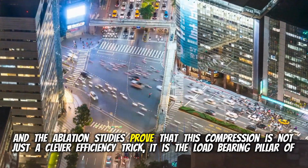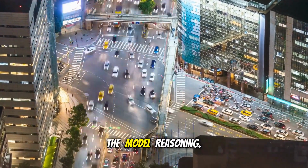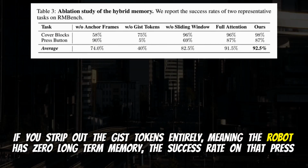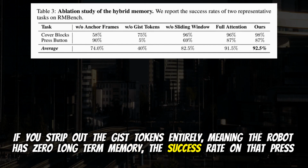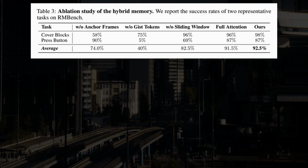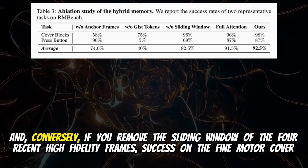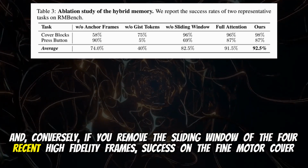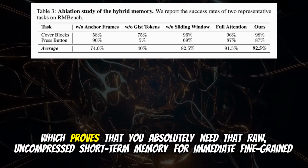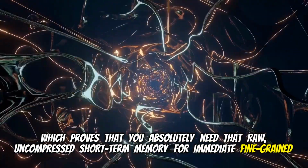And the ablation studies prove that this compression is not just a clever efficiency trick, it is the load-bearing pillar of the model's reasoning. Yeah, they ran the numbers. If you strip out the GIST tokens entirely, meaning the robot has 0 long-term memory, the success rate on that press button task craters from 87% down to 5%. It essentially lobotomizes the robot's ability to execute any sequence-based logic. And conversely, if you remove the sliding window of the 4 recent high-fidelity frames, success on the fine motor cover block task drops. Which proves that you absolutely need that raw, uncompressed short-term memory for immediate, fine-grained motor control.